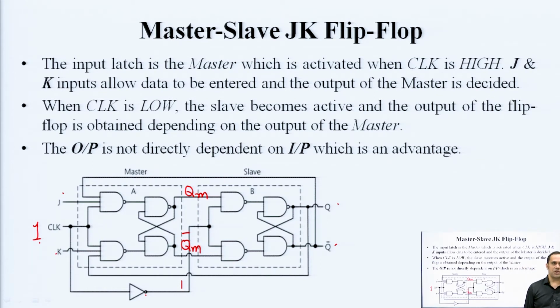For this duration of the clock pulse, when the master stage is inactive, you can have any number of changes in the primary inputs, you can have level changes, the level can still remain 0, the level can remain 1 after the inverter, but any change in the input will not affect your output, because this stage is now cut off. Now, depending upon Q M and Q M bar, and this cross connection of the actual output, your present or next state is going to be decided.